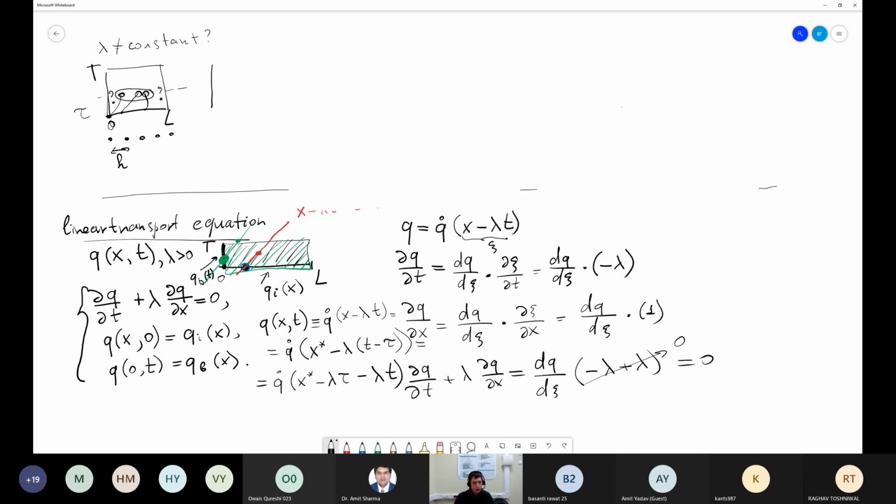The other method was proposed when we have some nodes here, x subscript i, and we set the initial condition of these nodes after some small value of time. We want to calculate the values at the same spatial positions. And to achieve this, we start from the next time layer and go back. That's why this method is called the inverse method of characteristics. We go back and find the intersection of this characteristic curve. We can deal with the nonlinear characteristics, something like this one, or something like this one.